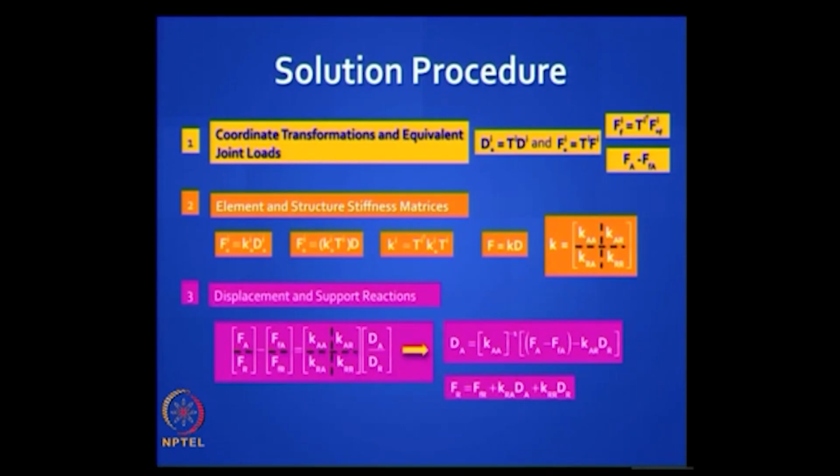Here you will find the displacements and support reactions using the equilibrium equations. Please note here the displacement vector contains dr, which is not 0, not a null vector, because now you have support settlement. So you have to be careful to include that.